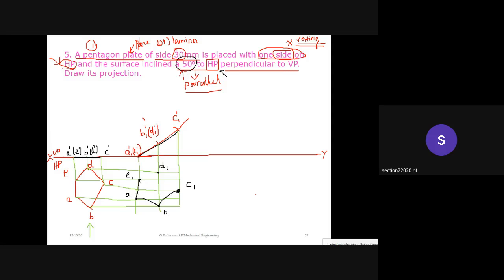Okay. Be very careful that the vertical projection line, see, so this line you're taking from the top, this vertical projection line should be perpendicular to your reference line, and this horizontal projection line which you are taking from this part should be parallel to your reference line. That is very, very important. Okay, so the black color one what I have drawn in the diagram should be darker. So only the black color thing in the diagram should be darker. All other remaining should be very light and very thin.